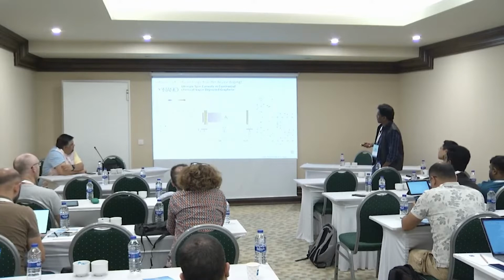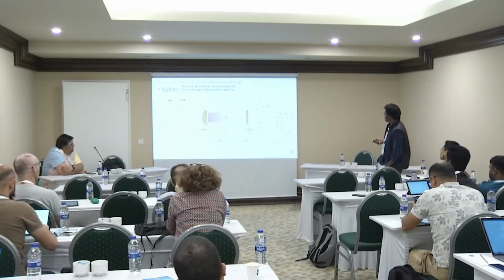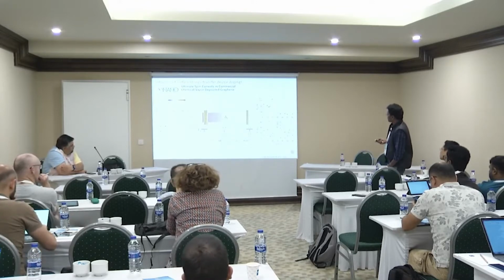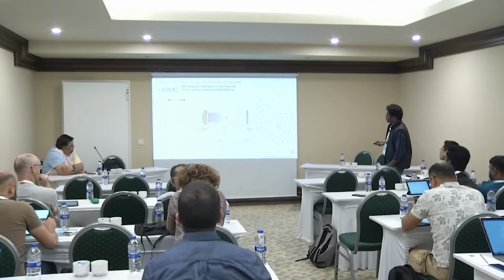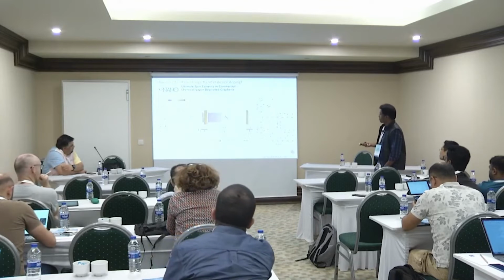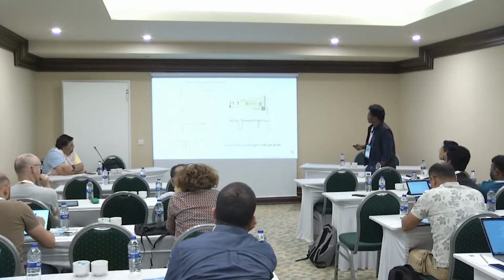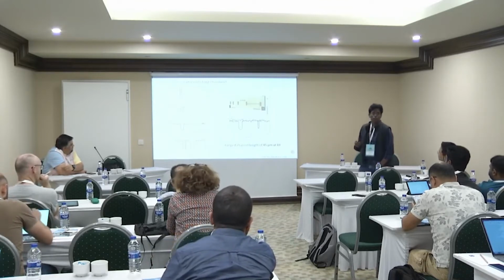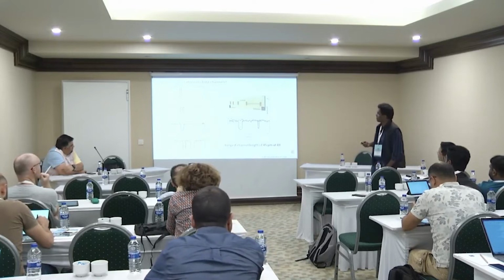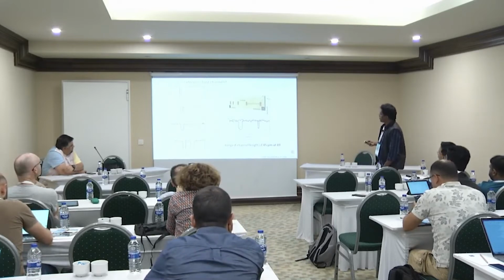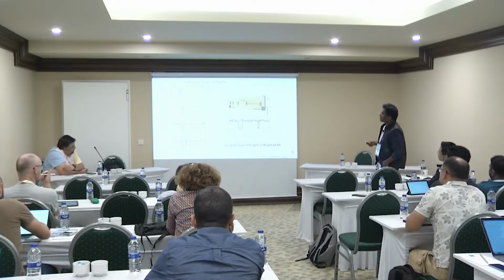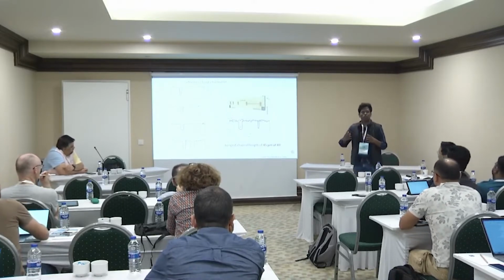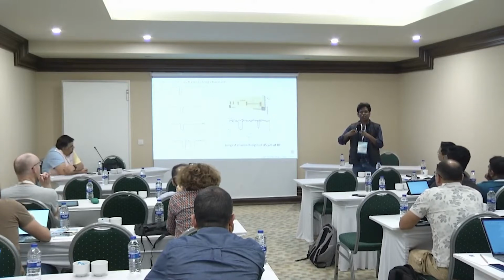As a consequence of that, what we see is that the sheet resistance of graphene changes also, and the contact resistance of these contacts with graphene also, the interface resistance also changes. So when we took this into account, we started to realize that we can keep electrodes very far from one another, and we started investigating extremely long channels that are much bigger than the kind of exfoliated graphene sheets that